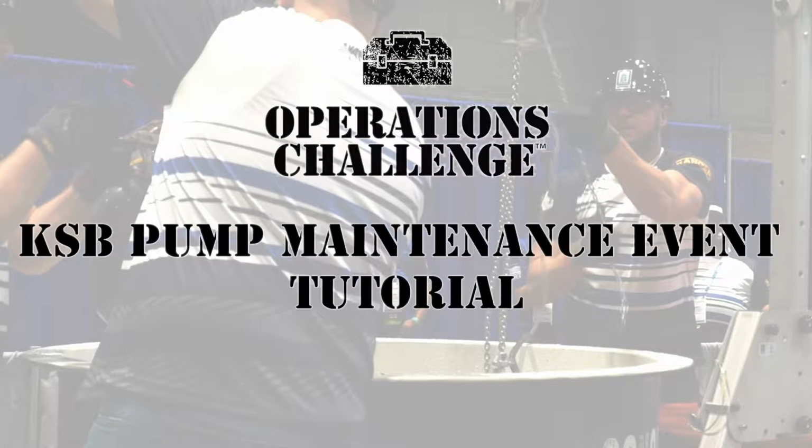To help combat this problem caused by these wipes, KSB has developed the F-Max impeller. The F-Max's asymmetrical blade arrangement offers a wide free passage for solids and wipes to pass through the pump. Additionally, the blades were designed to create a swirling effect around the shaft area to shift the flushable wipes away from the impeller and shaft and to the outside of the impeller for them to be pumped out. Teams will also be exposed to an emerging trend in safety in electrical work, and that is arc flash.